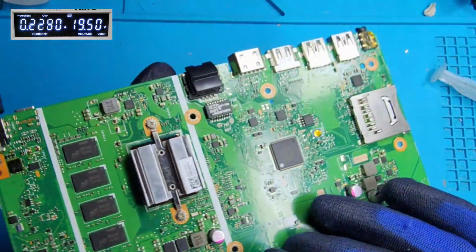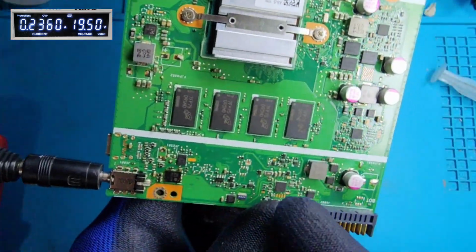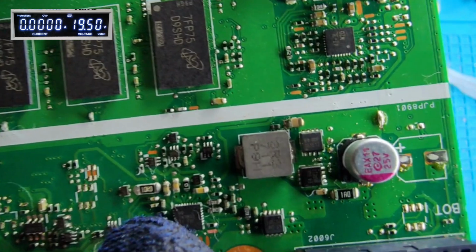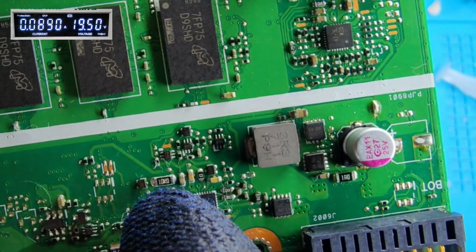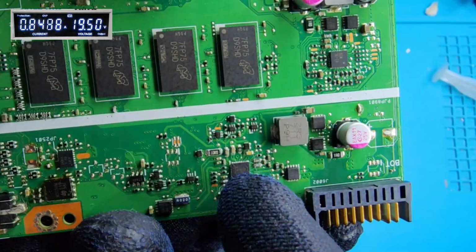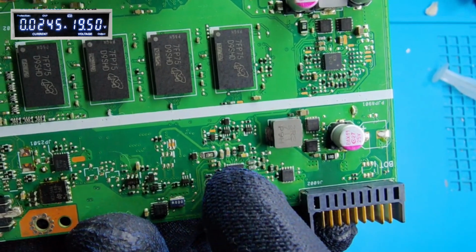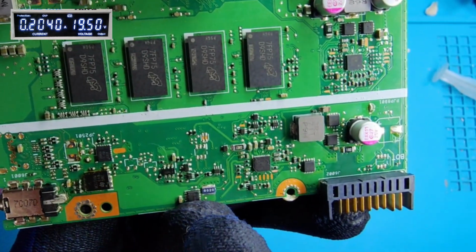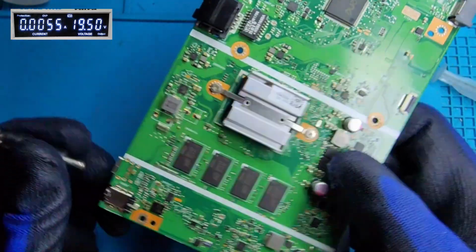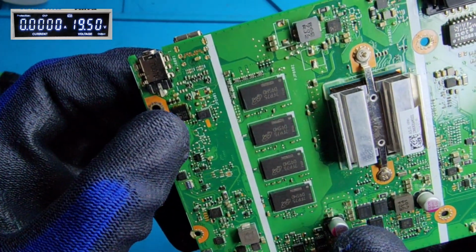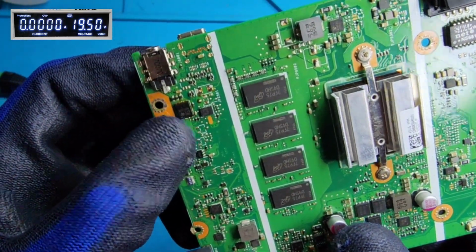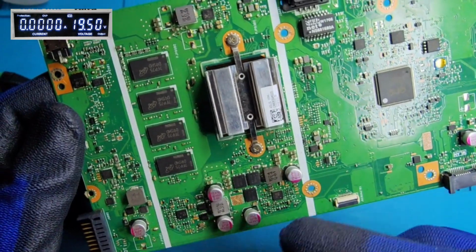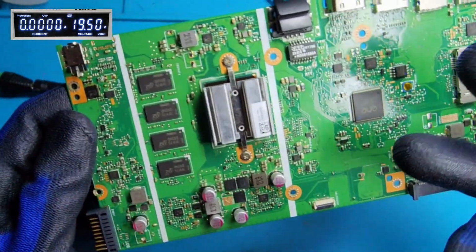So this resistor was faulty. Which one is here? The 10 ohm resistor. It was 188 ohms. The power for the charger IC was not enough to provide the gate voltage for the first and second MOSFET. So I just shorted the first and second MOSFET for checking purposes, to see whether the main power relay is okay and if it is working fine.